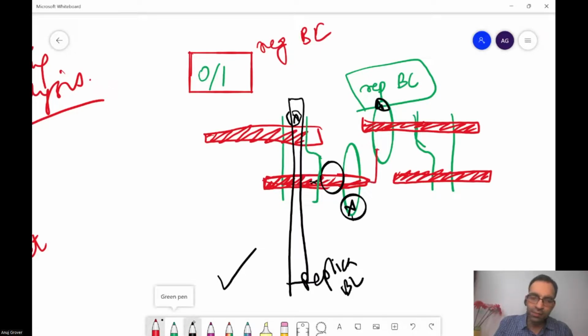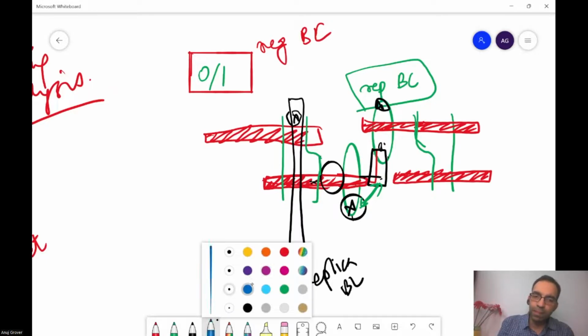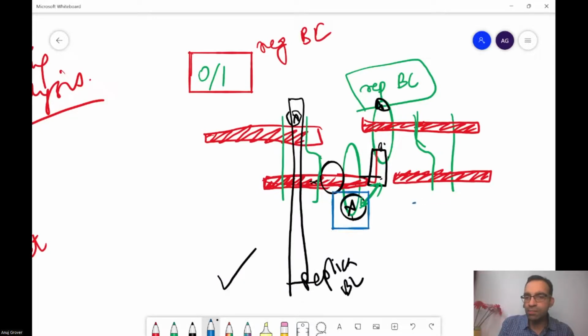There is a long contact between this poly and the active over there. One way you could say is, okay, I will simply create a short between the two of them. But to be able to do that, you will have to cut metal 2 somewhere, metal 1 over here somewhere. So when you open the layout, जो हमने class में भी देखा था view, you will see that there are metal 1 stubs here, there is a metal 1 stub over here for the bit line, and so on. So it is not easy to connect this metal 1 stub to this metal 1 stub. It can lead to DRC errors there.